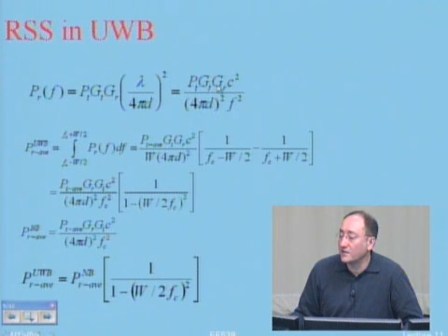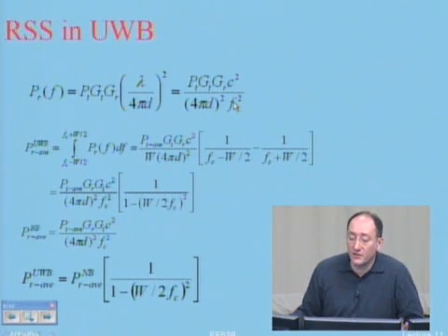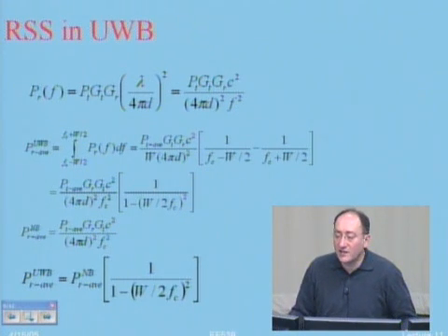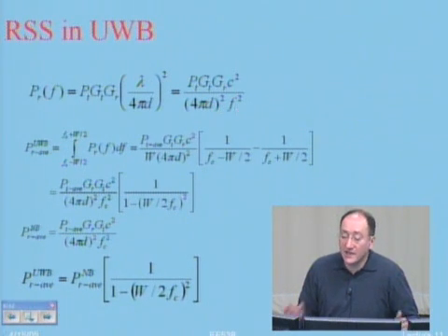This is the gain of the transmitter, gain of receiver, transmitted power, these are constant, this is the distance, this is the speed of light. f is the only variable in here, which is the frequency of operation. Normally, when we were doing our calculations for all the systems, we were assuming that f is your carrier frequency, which is the center of your bandwidth.